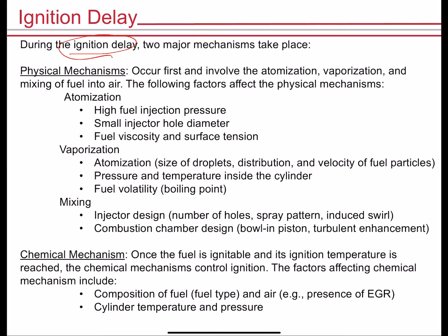And the various factors that affect atomization are things like the fuel injection pressure, the diameter of the injector holes, and the fuel fluid properties, like fuel viscosity and surface tension. Things that affect vaporization are the extent of the atomization, the size of the droplets, the distribution, the velocity of the fuel particles, pressure and temperature inside the cylinder, and fuel properties such as fuel volatility, the boiling point of the fuel.